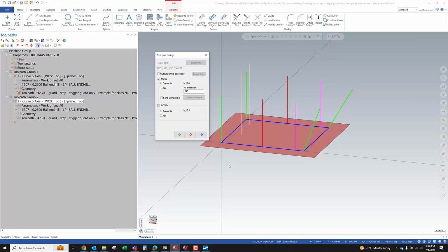So we can, for example, set up a UMC 750 5-axis, put a part in a vise at the center of the table that's not precisely dialed in, let's say, and we can measure what the rotary correction on the C-axis would be. Say it's negative, I'm going to make up a number, 1.28 degrees.